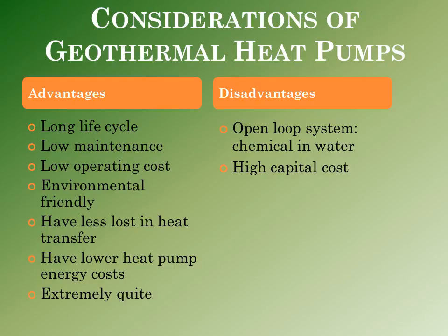The disadvantages are that in an open-loop system, the machine parts need to be protected from corrosion and require periodic acid cleaning since they are buried underwater. Over a long time, the chemicals in the water can actually make it difficult for the system to exchange building heat with groundwater. Moreover, the installation capital costs of geothermal heat pumps are quite high.